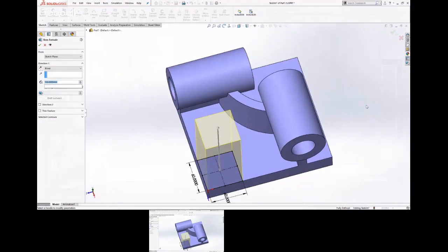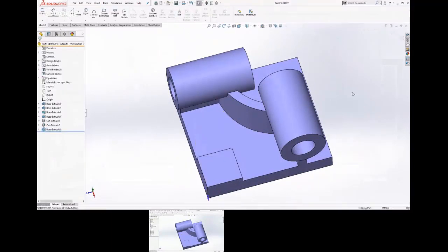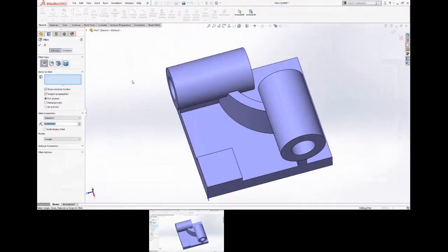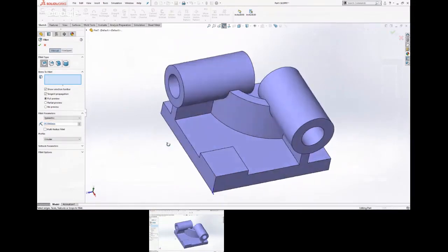So this is just going to be a simple 10 millimeter extrude, just like that. And then we'll add this fillet in. I know I called it out, it's a 15 millimeter fillet. Yep, actually now I'm remembering this morning I did it because I remember selecting through. Everybody have that option to turn on selection through faces, select edges through faces?